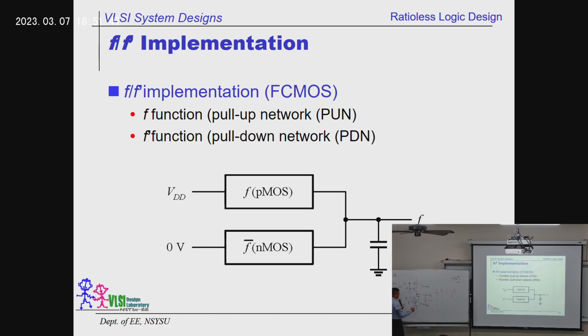However, by contrast, there is a path to discharge the charge on the capacitor to ground. So in this way, we find out if either one of them is 1, we are going to have 0. Of course, if both transistors are on, we are going to have 2 paths to ground this output voltage to get 0.